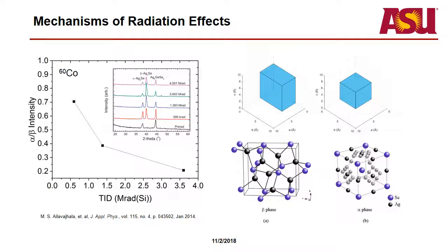And so essentially, the beta phase is in a bulk silver selenide compound. It's going to be the dominant phase. And so this is silver that's covalently bonded to selenium. This is silver 2 selenide, but it's more of a semiconductor. And then once you get over, say, around I want to say 350 centigrade, you transition to the alpha phase, which is a body-centered cubic with interstitial sites that the silver can loosely bond to.